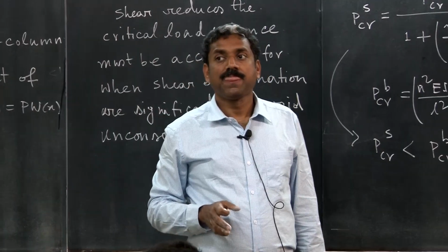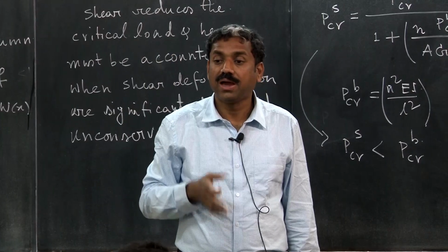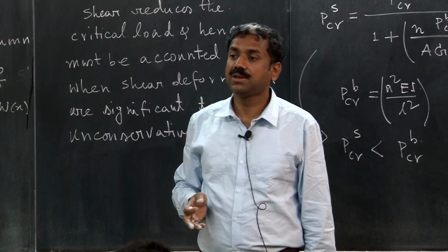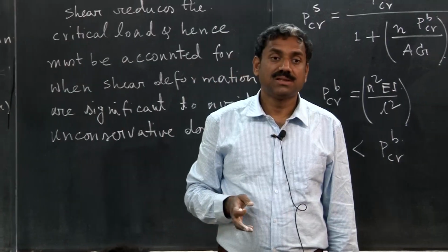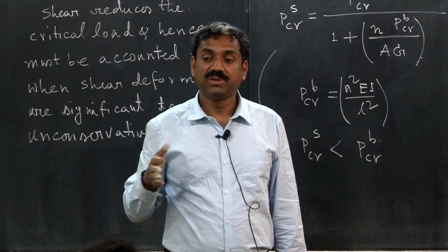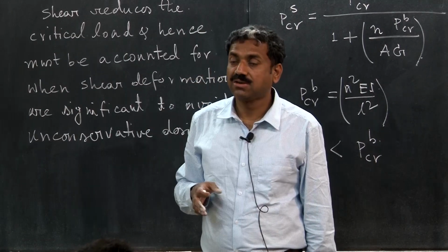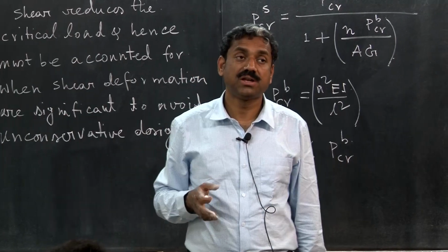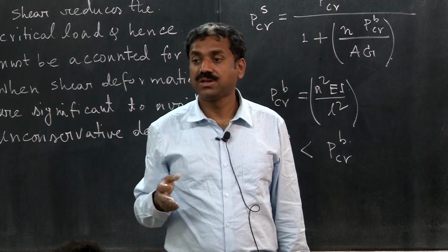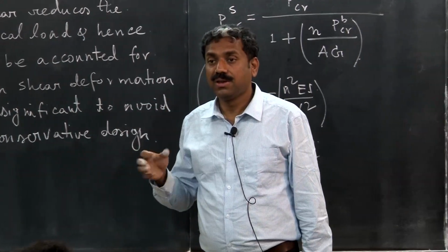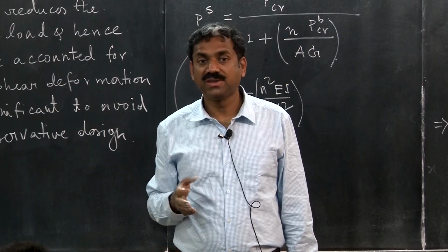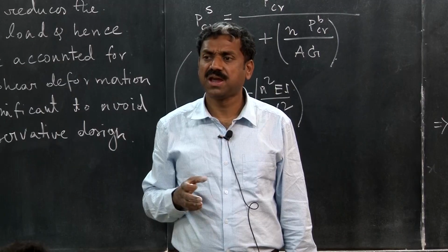So, for that people introduced higher order shear deformation theory, that is, beyond first order shear deformation theory, and that is where Reddy's higher order shear deformation theory and Professor Kant's shear deformation theory come from. All these theories are not asymptotically consistent. There are asymptotically consistent shear deformation theories by Babuska. All these theories demonstrated the influence, and it has been a very hot topic, very easy topics for PhD. Many PhDs have been guided on this.